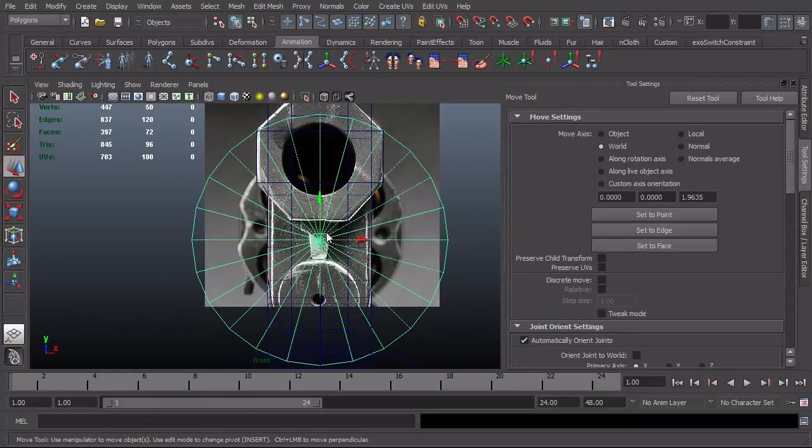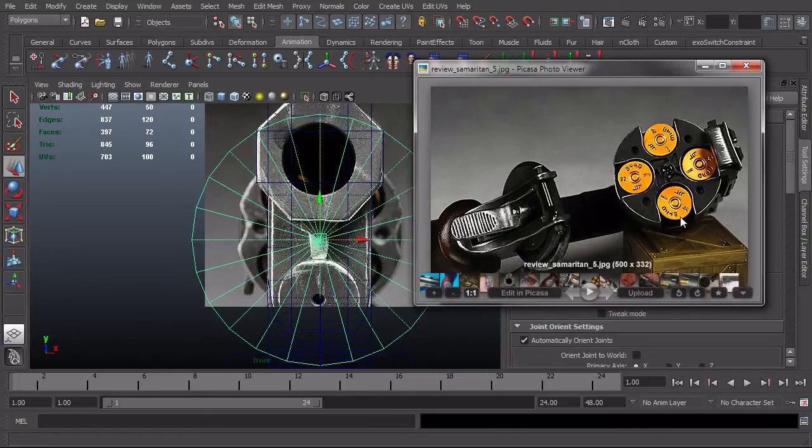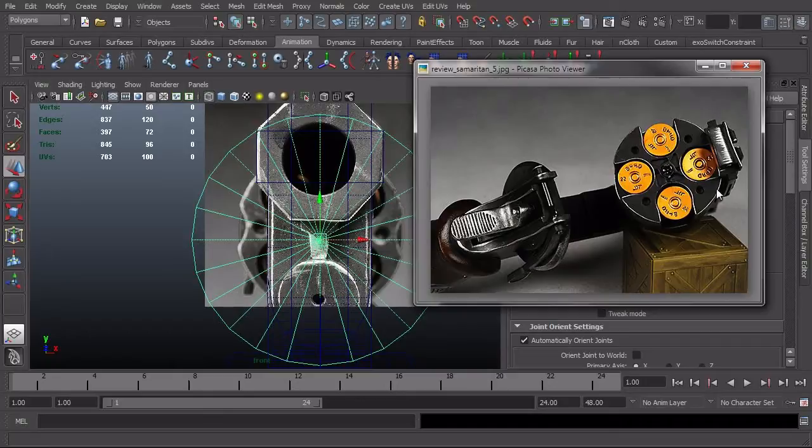Besides just your relative resolution, take a look at how you're going to actually construct this thing. So for instance, if I cut this thing in half vertically, then I only have to model half. But in this case, it basically can be cut horizontally as well. So all I need to do is model this quarter and then just mirror it down and then mirror it over, and I'll have the whole piece.